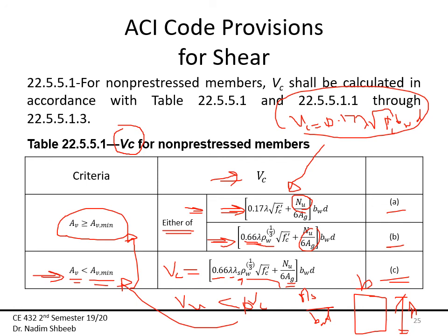In certain cases, you're talking about in the order of maybe 20 to 30 kilonewtons, which sometimes could be the difference between using stirrups every 10 centimeters, every 8 centimeters, or every 20. So just to let you know on that, and we'll talk about this more in the ensuing examples.